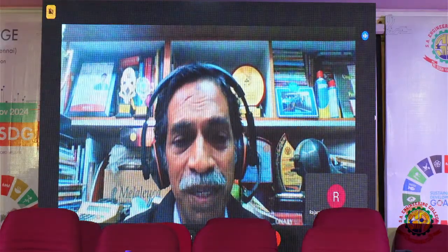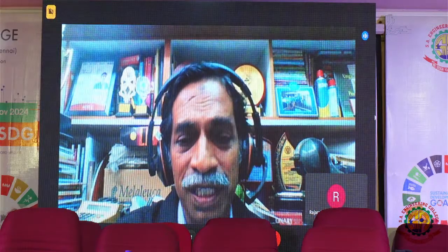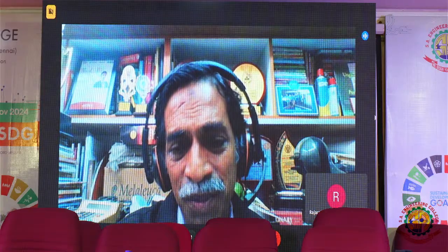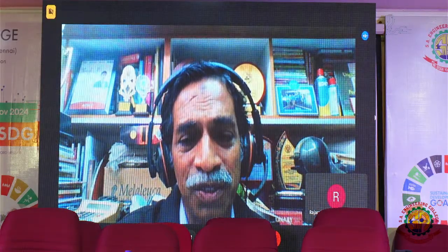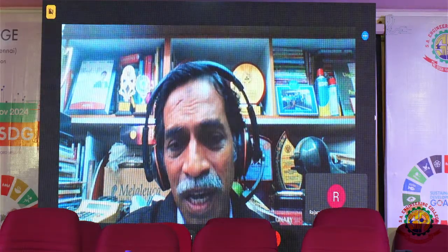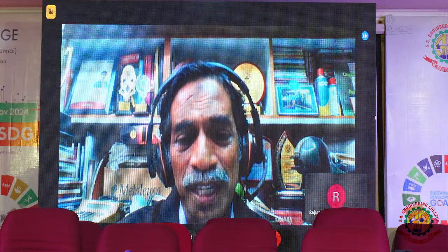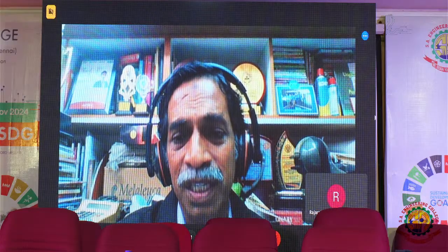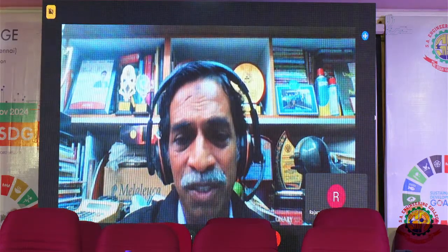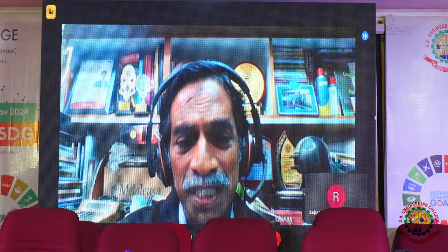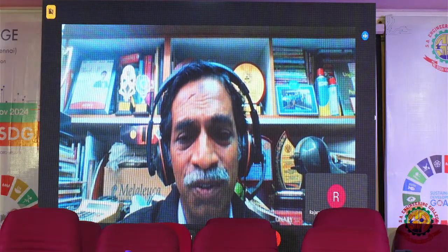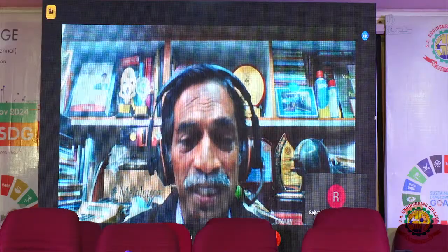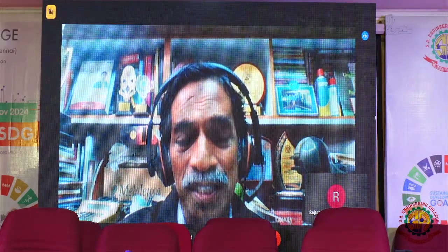And this is a typical architecture. You see here, number one, you collect the sensor inputs, in this case temperature, humidity, and CO2. You send them to this control panel. And from this control panel, you send to the cloud. And from the cloud, you can access from your handphone, your PCs or tab. Most of the decisions are made in this cloud. You have all the tools, decision support tools, image processing tools, and things like that. So you make all these decisions in the cloud.